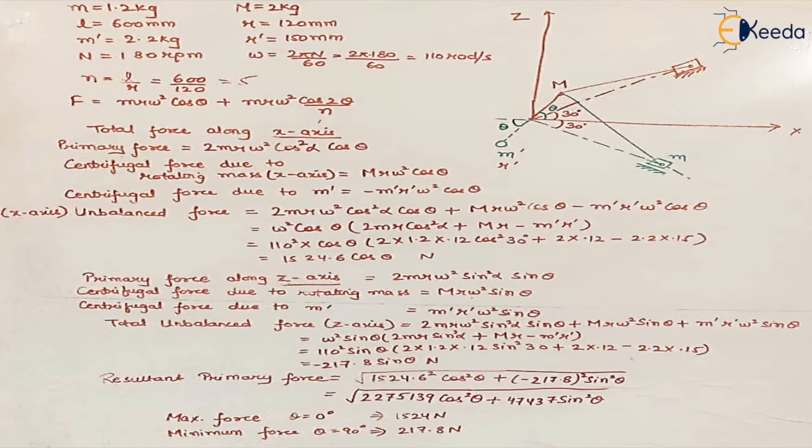We have got the two cylinders, right? And the mass of both the cylinders is denoted by small m, which is 1.2 kg. They have a common crank and the mass is given as capital M, which is 2 kg. The length of both the connecting rods is small l and the length of the crank is small r. And in the question it is given that to balance the unbalance produced because of the reciprocating and rotating masses, there is a counter mass which is being added opposite to the crank. So this is the counter mass, and this mass is m dash